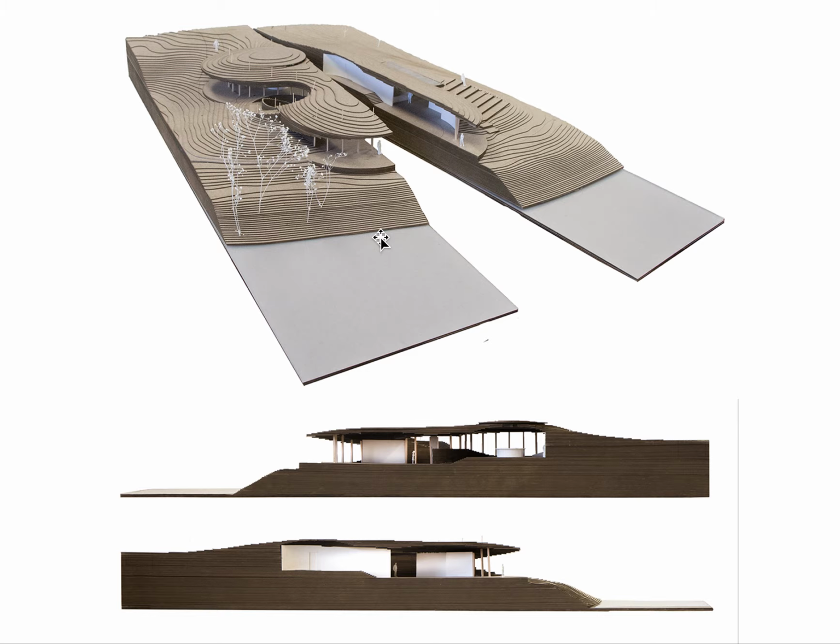So this clearly, in this case, is about a foot. So these contours are a foot. So you see how close they are together, how many there are, because they're only a foot apart. In this case, it was necessary to build a model that had a three-dimensional solid feel to it to get them close together. But most likely you would not have that many contours on your site plan itself.